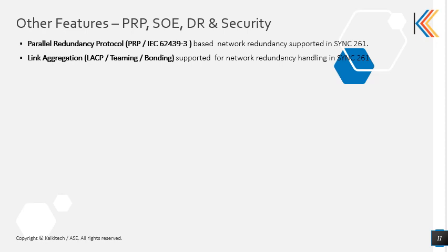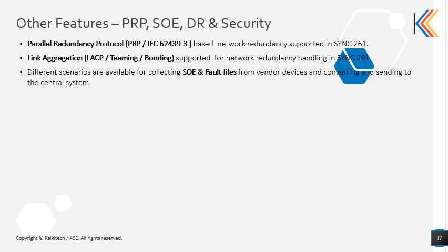Then we also support the link aggregation LACP protocol, or the common terminology is teaming or bonding. So this is another mechanism of supporting redundancy or putting more throughput onto the interface. So this is also supported in the SYNC261 device. Then different SOE, sequence of event, and fault file collection mechanisms are supported.